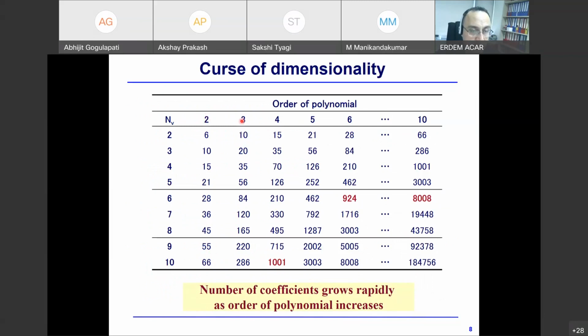Now, if we increase the power of the polynomial from 2 to 3, then the number of data points required increases from 100 to 400. So if we have this computational budget, then we can go with third order polynomial. But usually people use second order polynomial, at most third order polynomial. Because for this 10 variable problem, if you increase the power to 4, then the number of coefficients is 1,000. So you have to perform at least 1,500 simulations. That seems too much.